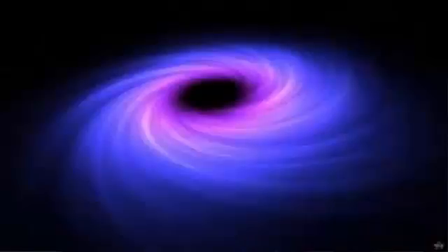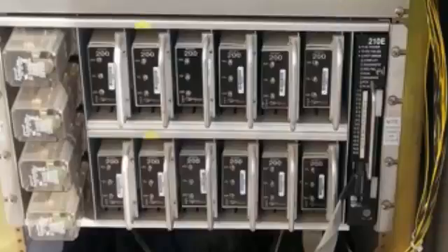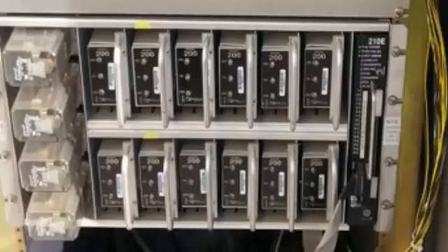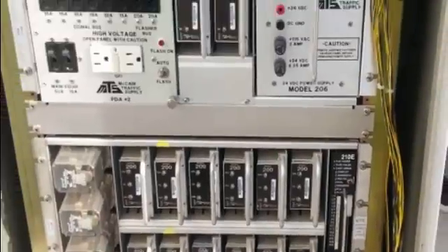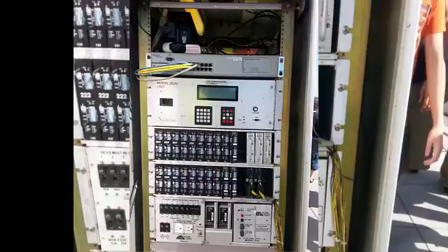Number 2, to check for absence of a red indication on a phase that does not have a green, a yellow, or a walk. Number 3, to check for insufficient operating voltage that is usually due to power interruption. Upon the detection of a malfunction, it immediately places the intersection into latched flashing operation, which basically means all lights flash red.